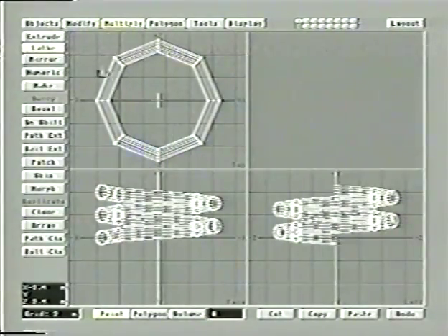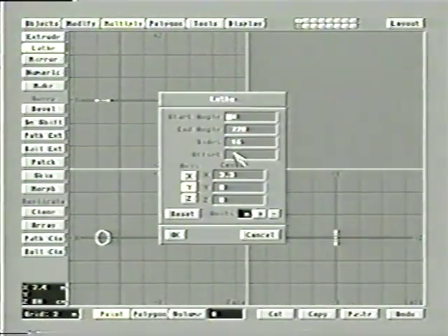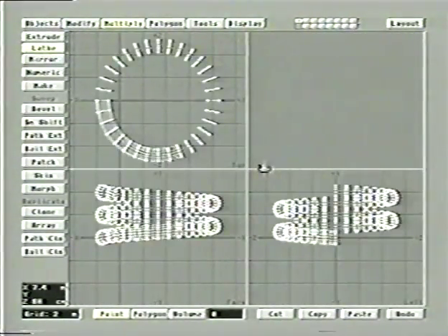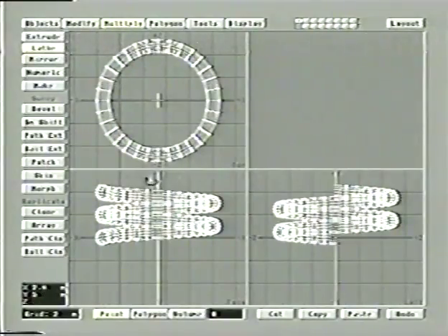The problem is, from the top view, it's very squared off. And the solution, of course, is to raise the number of sides. Remember, the fewer sides, the less round something is. The more sides, the more round it is. So the reason it looks flat is because we're doing 2 complete rotations and raising it with only 16 different segments. Not going to work. So let's undo, raise our number of sides to 64. Now you start to get the idea.